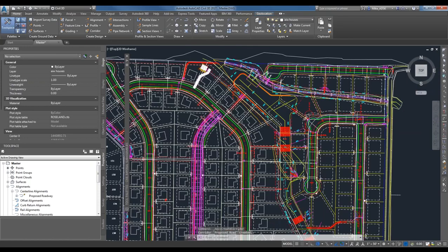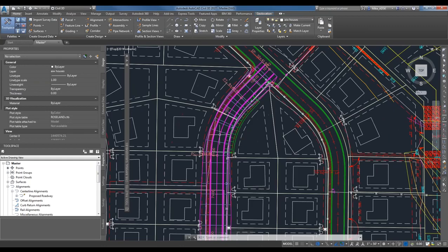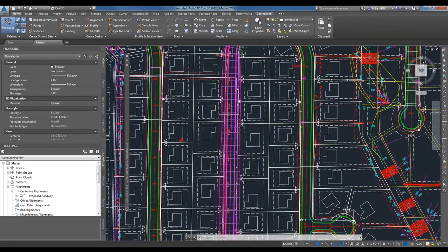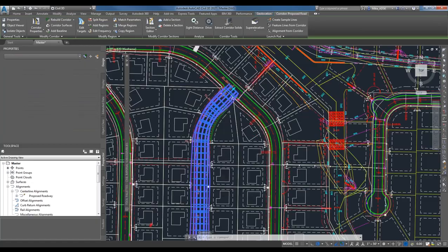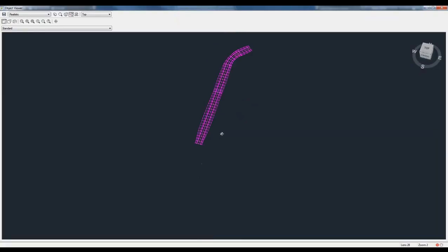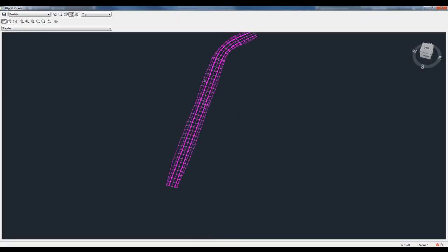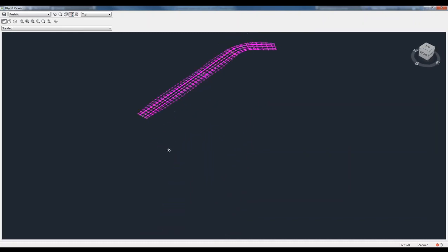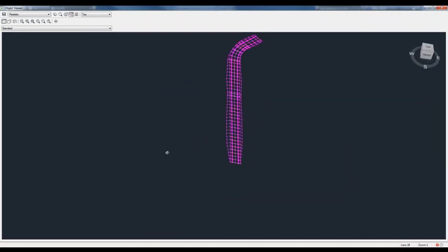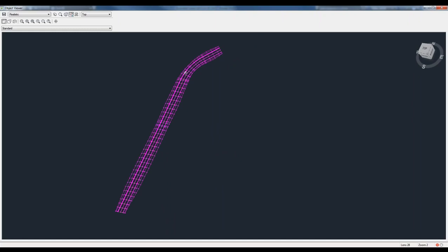And now you're going to notice that there's this pretty cool guy right here. That is our corridor. So now we've actually created our corridor. This is taking basically our alignment, which is straight across the horizontal, the profile vertically, and then each spot where you see those lines, that's where our assembly is placed.